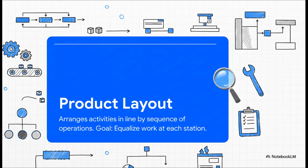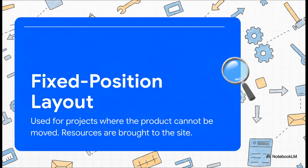The product layout is what pops into your head when you hear the words assembly line. Here, everything is arranged in a straight line, following the exact sequence of operations needed to make a specific product. It's built for speed and efficiency, perfect for continuous mass production. Now, the absolute key here is that the main goal is to perfectly equalize the work at each station. We call that concept line balancing. And our third basic type is for those situations where the product is just way too big to move around.